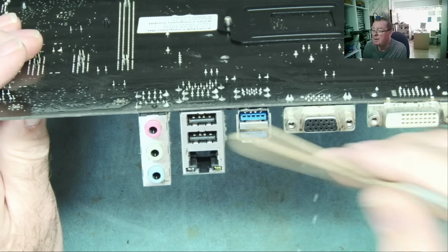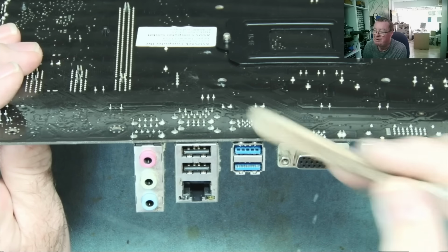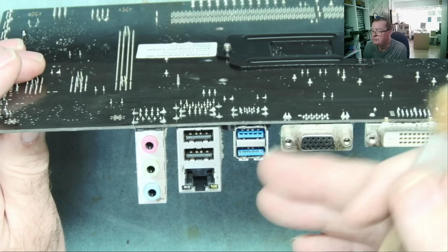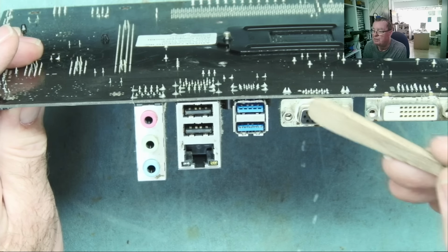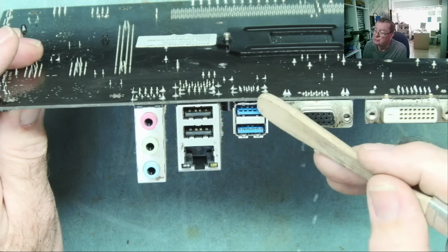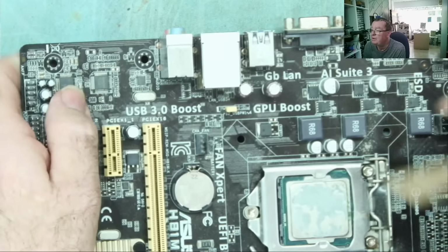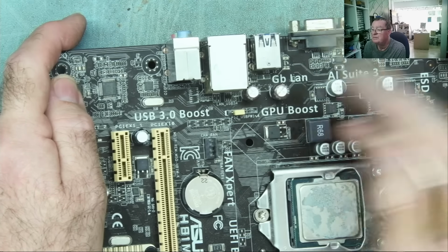USB, HDMI, these are prone to the same failures, but the most common failure with these is user failure, because the user has plugged the thing in hard, forced it to go in when it's not located right, and they've bent pins. That may well short out pins or short them to each other, which in turn may then blow the chips which are connected to these the next time you power up.